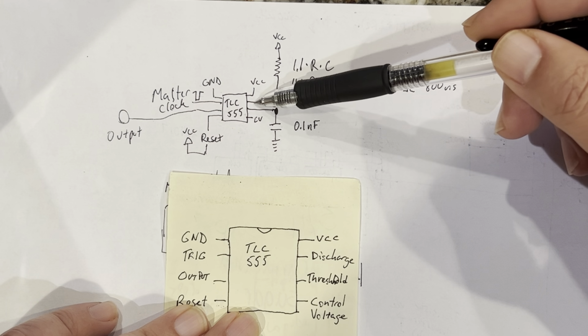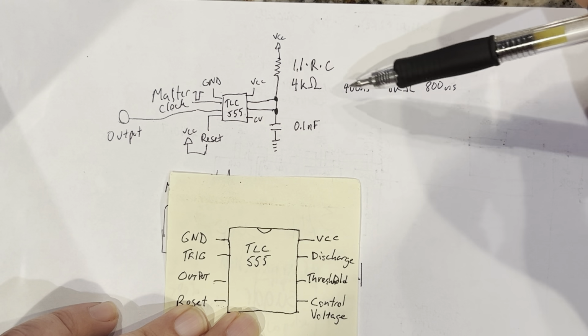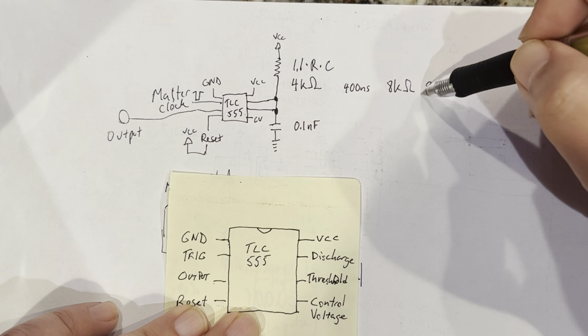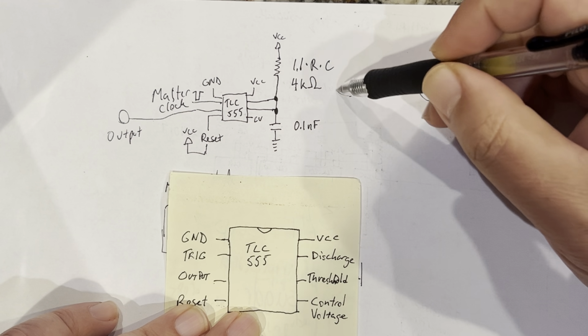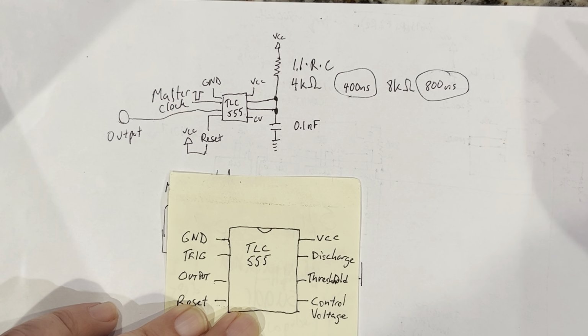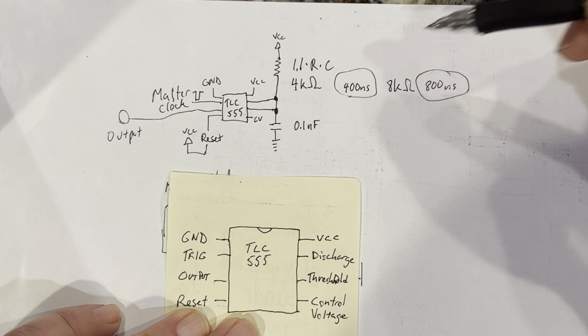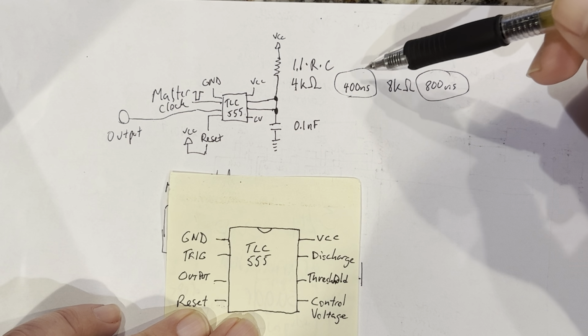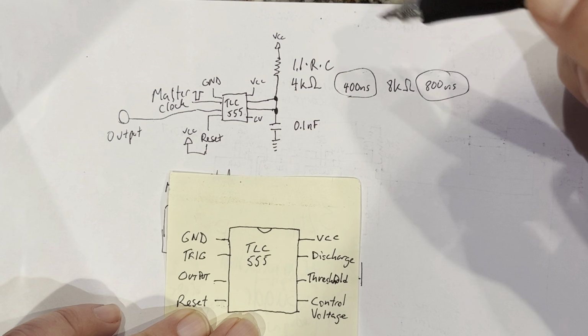If it takes a whole microsecond to turn a comparator on or off, and you're trying to generate signals that are less than a microsecond long in monostable mode, you're not going to be able to accomplish this.